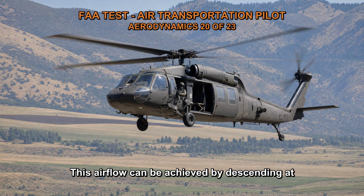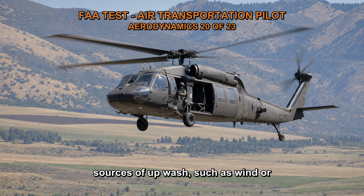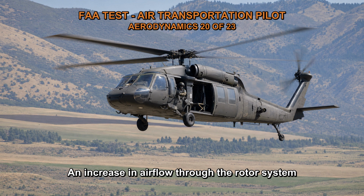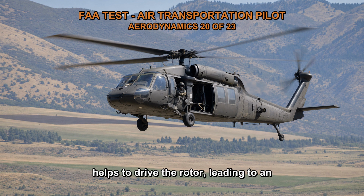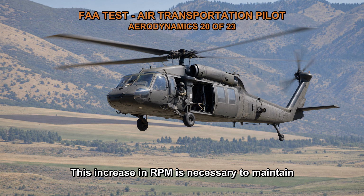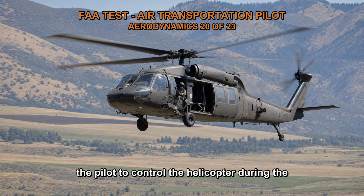This airflow can be achieved by descending at an appropriate rate or by utilizing any available sources of upwash, such as wind or the downwash from the helicopter's own descent. An increase in airflow through the rotor system helps to drive the rotor, leading to an increase in rotor RPM during an autorotation. This increase in RPM is necessary to maintain rotor energy and sustain rotor authority, which allows the pilot to control the helicopter during the descent.